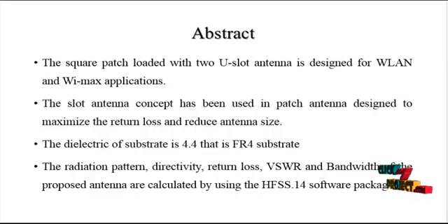while the second one is the dimensional invariant, the DI method, which relies on the property of DI to design the U-slot microstrip patch. In both of these methods, the optimization of the probe location is necessary for further enhancement of the 10 dB return loss bandwidth.